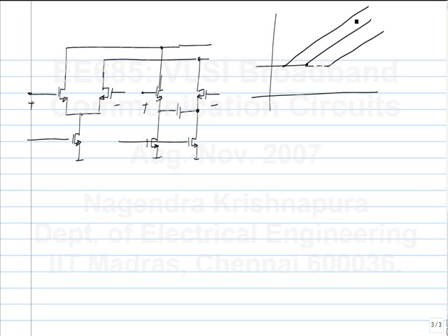How can you get responses this way? What do you have to do to the circuit to get this response, either with this or the previous topology? Yeah, you have to either change the capacitance or the resistance in parallel with it or something. Effectively, they are the same thing. Okay, it's not very convenient as with the other case where you just switch the tail currents and the coefficients vary directly with the tail currents, but you can do that. Okay. Any questions on this continuous time implementation of the equalizer?